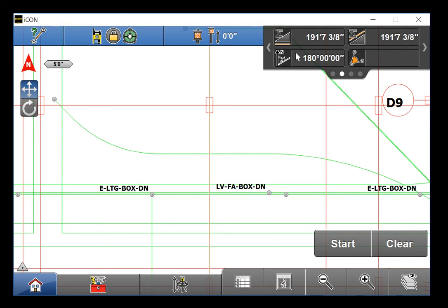The lower left box contains the azimuth of the line selected. If your DXFs were not drawn or rotated to state plane coordinates, these azimuths do not reflect degrees turned from true north. But if you're doing calculations longhand, they can still be used in relation to the building. The lower right box contains theta, or the angle between two lines selected when you have more than one line selected.